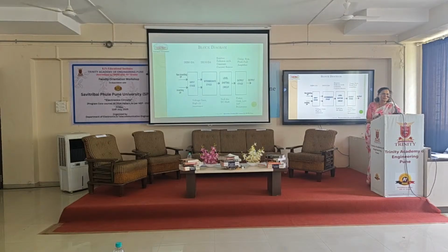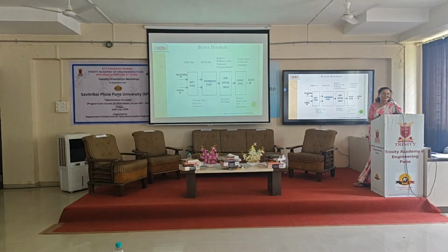That is starting from the block diagram. Here we have to mention the use of each and every block. The first two blocks are related to the differential amplifier. Third is the level shifter, and the fourth one is the output stage, that is the complementary stage.